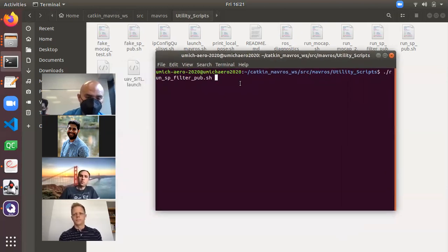When I run this, it's going to read the local position of the quadcopter, and that's going to be the basis. As in, it's going to add all of the set points to that initial position. The initial position is taken from when you first call this function. So you can move it around. You don't need to turn it off. You just need to take into account that this only affects the first position it gets when you first call it.